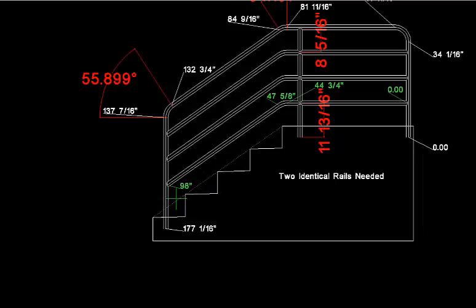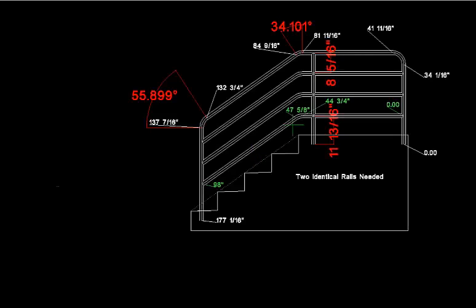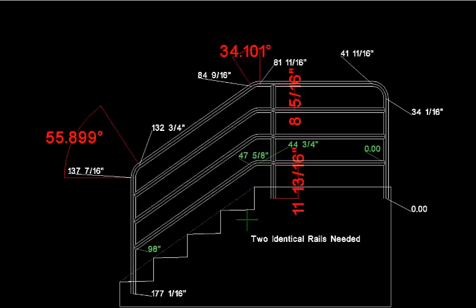One thing to remember, when you're making this rail coming down, this step here sticks out a little past. This one does too. It's important that your rail, if anything, is sloped a little further down than it's supposed to be. Never send a rail up high. If this angle is greater than the slope of the steps, it looks terrible. If it's down too much, you really don't see it, and I've never heard anybody complain. The other way, I've had people complain. So that's just something to keep in mind.